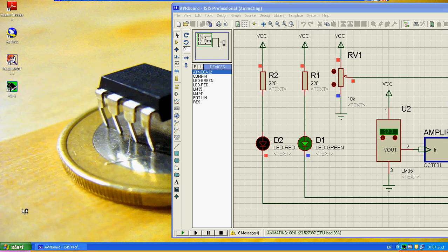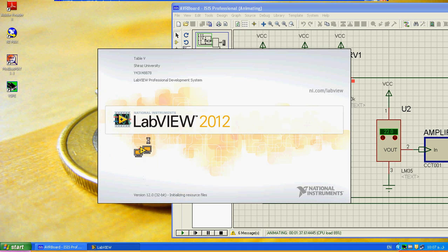Okay, we run National Instruments LabVIEW 2012. As the splash screen appears, you can see the LabVIEW 2012 registration codes, and there should also be an icon on this splash screen that you can see here. There are 2 computers with an op-amp sign on them. It signals that LabVIEW 2012 is equipped with the DSC, Datalogging and Supervisory Control module, which is required for LabVIEW to become a Modbus master.